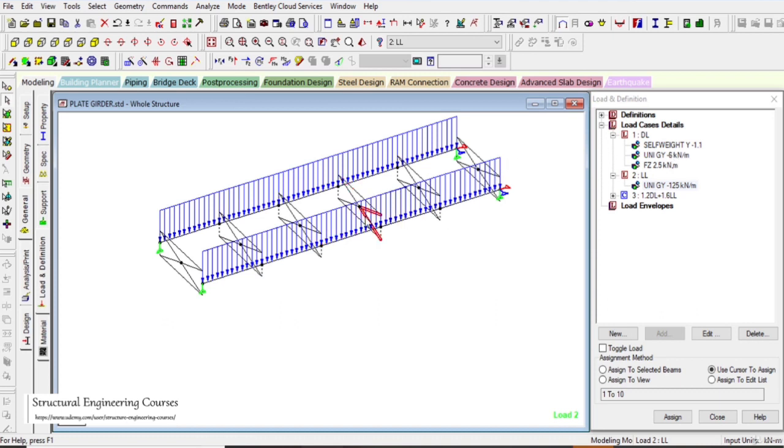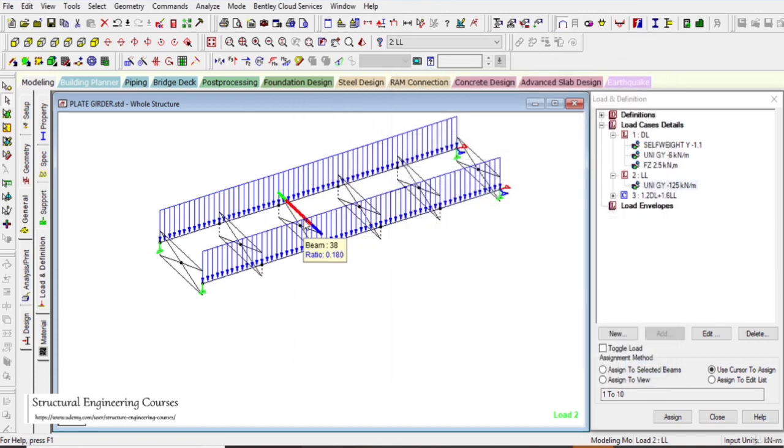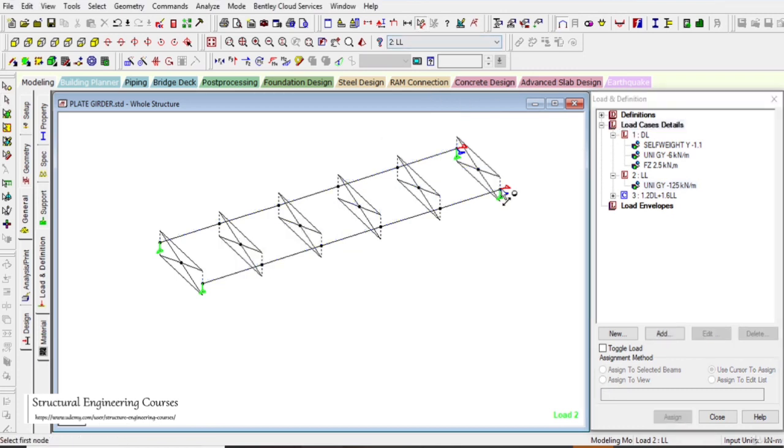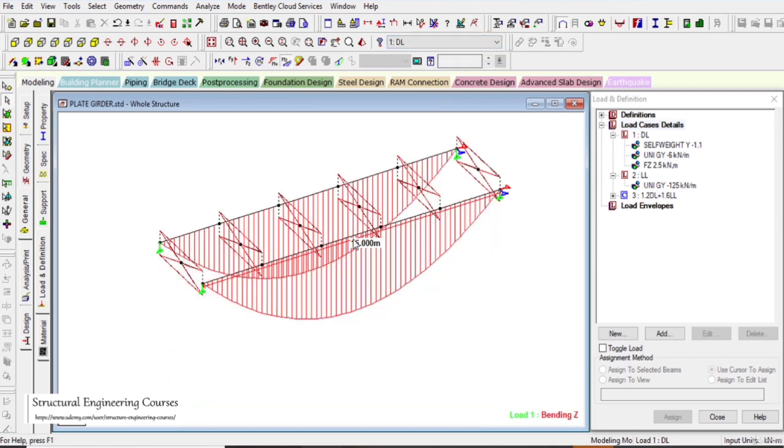And if we want to see this bracing arrangement here, you can see the simple MY and FX values. And here we can see that the ratio of this is only 70%, and the ratio of this girder here is approximately 80%. So this is basically a single girder only from this point to this point. But due to this bending moment profile, the maximum bending moment is around here, and the minimum bending moment, that is 0, is at the support sections.